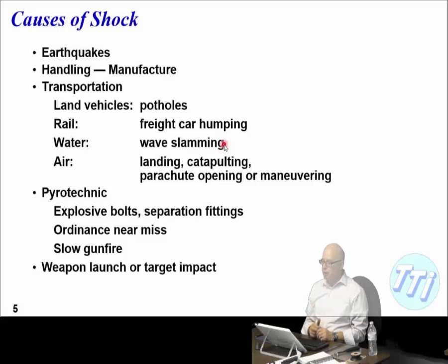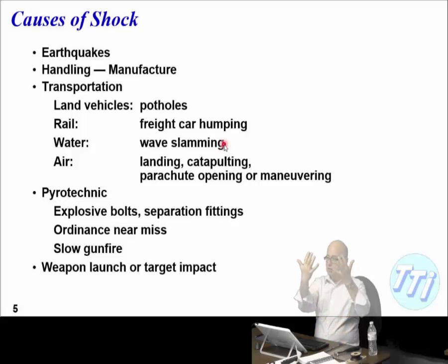But there's two different kinds of slamming that we can get there. The one is where we call it shipping green, and you've probably seen pictures where a ship plows into a deep wave and disappears underwater. Basically becomes a submarine for a short while. If you're up on the bridge of those ships looking out there, what you see is this wall of water just slowly come at you. And then you get this bang, as these tons of water hit the front of the deckwork. And that sends a violent shock through the ship. And then hopefully the ship comes up ready to plow onto the next one.